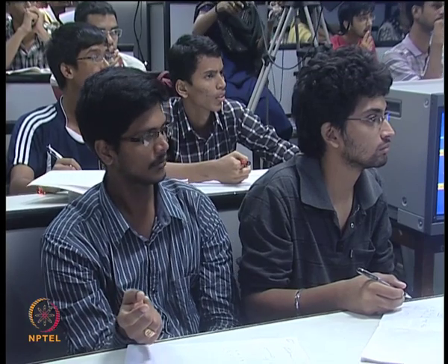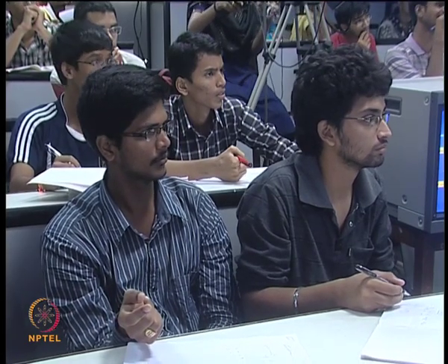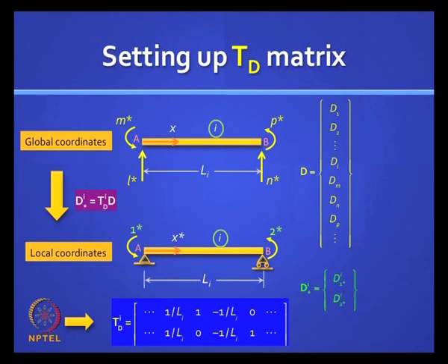This is this portion. Let us try to figure out. It is very easy. If I lift this up, that is my first coordinate, dl, by unity, do I get a clockwise chord rotation? Yes. So I get anti-clockwise end moments, which are positive. So the equivalent rotation is positive.